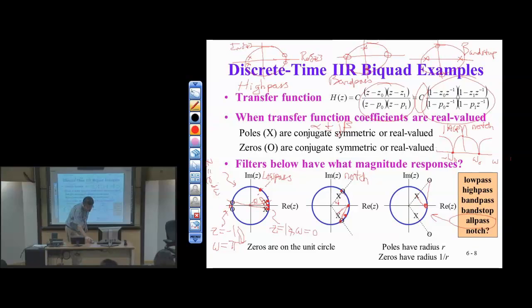All right, so that's the way we're going to implement it. In practice, if we go with really high order filters, 10th order IIR, 12th order IIR, we're better off with cascaded biquads. And if it's 9th order, then we'll have 4 biquads and a first order section. It's a lot more robust, and we'll talk about why that is now, I guess.